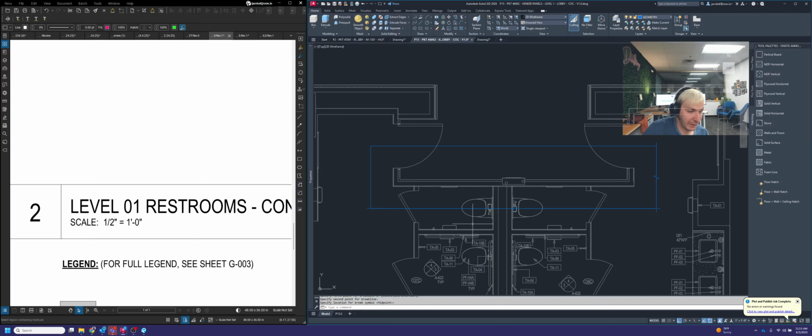We have talked about the break line command before, but when you go to start it, it's going to ask you for 2 points. So you always pick the 2 corners of where you want the break line to show up between. And then it's going to ask you for the midpoint of the zigzag or the break symbol. If you don't click on any point, you just hit enter, it's going to default put that break in the dead center of the break line. So just like that.